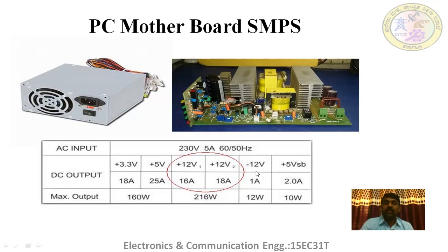And we know that in order to turn on the CPU, it is required to push the power button. Once you push the power button, this is the voltage supplied to start the motherboard. This plus 5 volts is called standby volts with high current. So this is assigned for the power switch of the CPU. So this is about the different voltages and the purpose of these voltages in the motherboard.